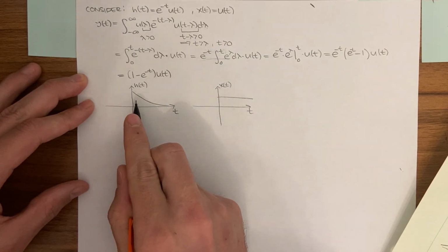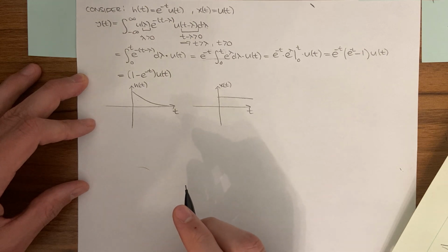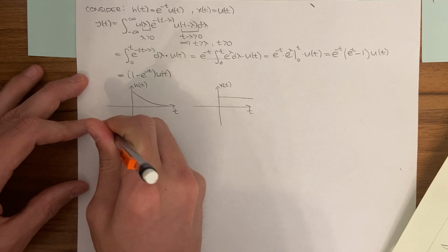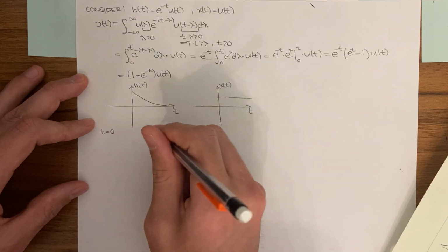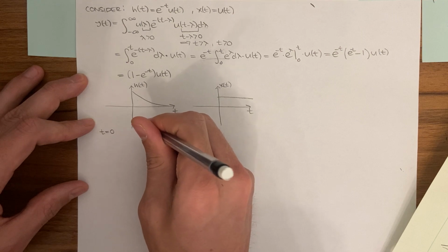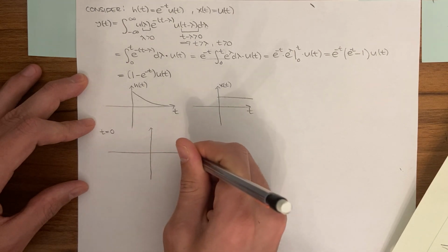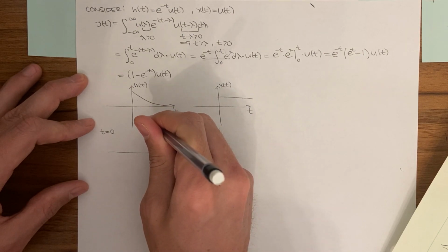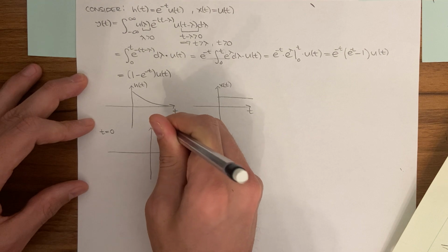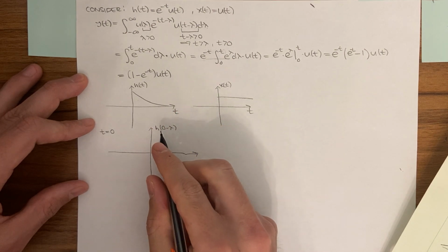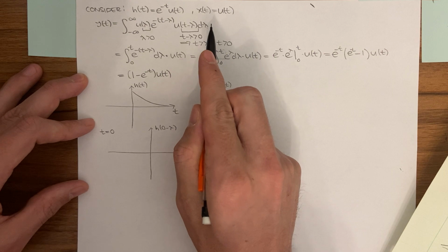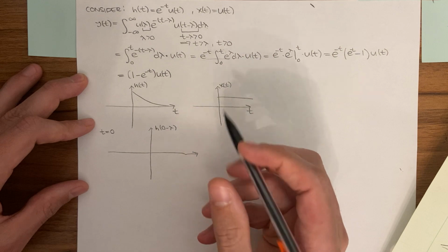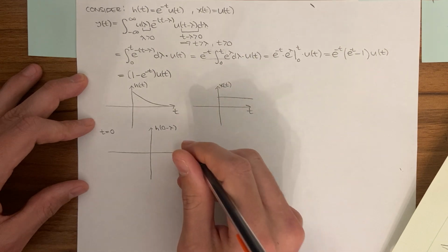Okay, so this is the decaying exponential, and this is just a step function. What we can do is draw the whole thing where t equals 0. If t equals 0, we have two functions we need to be concerned about. Remember, it's 0 minus lambda, because the expression in the integral is going to be h of t minus lambda. So we let t equal 0, and we plot against lambda.